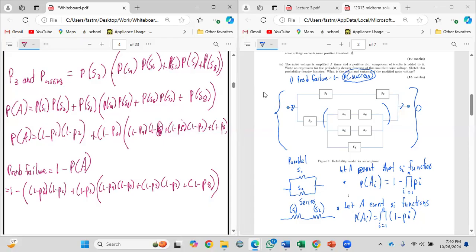So let's run it through one more time. So you have the circuit here. The first thing you do is get the Boolean expression. So this series you multiply, it's in parallel with S3, so you add, so it could be open bracket S3 multiplied by this parallel combination, so it could just be this in series plus this in series plus this, which is this piece here.